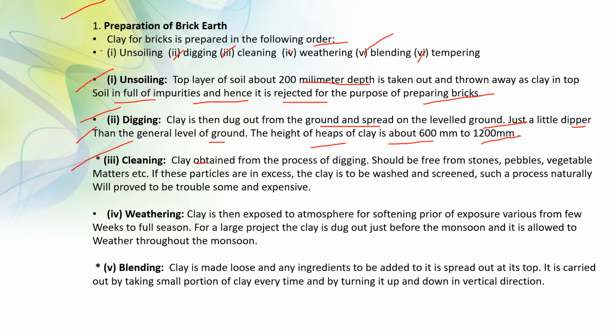Then what is cleaning? Clay obtained from the process of digging should be free from stone, pebbles, vegetable matter, etc. If these particles are in excess, the clay is to be washed and screened. Such a process will naturally prove to be time-consuming and expensive.